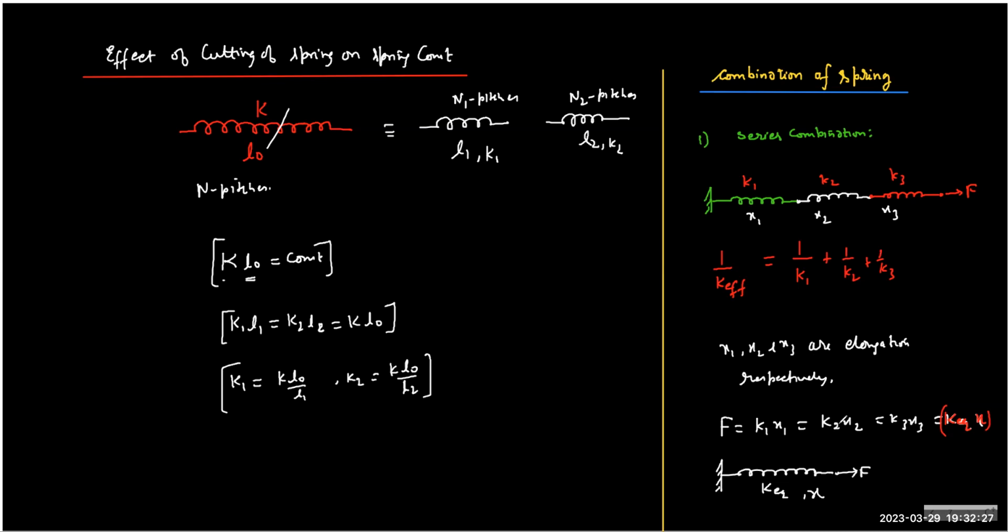The criteria is that the deformation in the actual case or in this hypothetical case must be the same under the same force, right? So the criteria which will decide the equivalence is equivalent deformation ability under the same force. So the X, as if this hypothetical spring will elongate, must be equal to the net elongation you achieved previously.